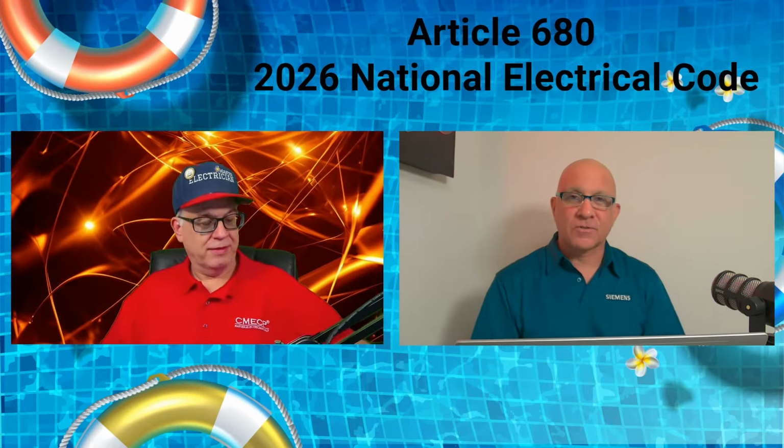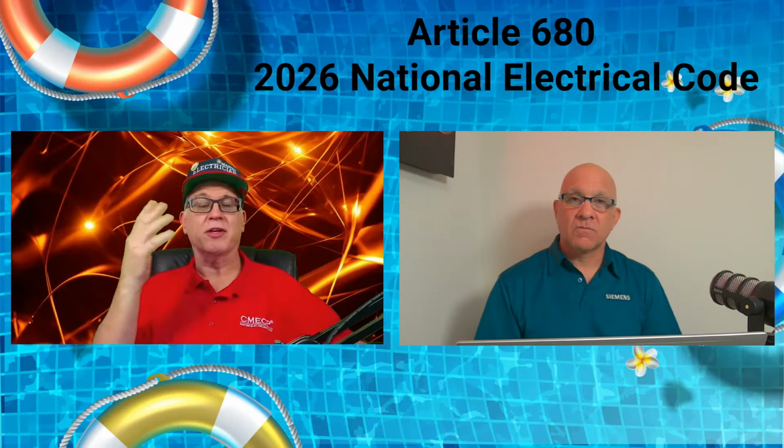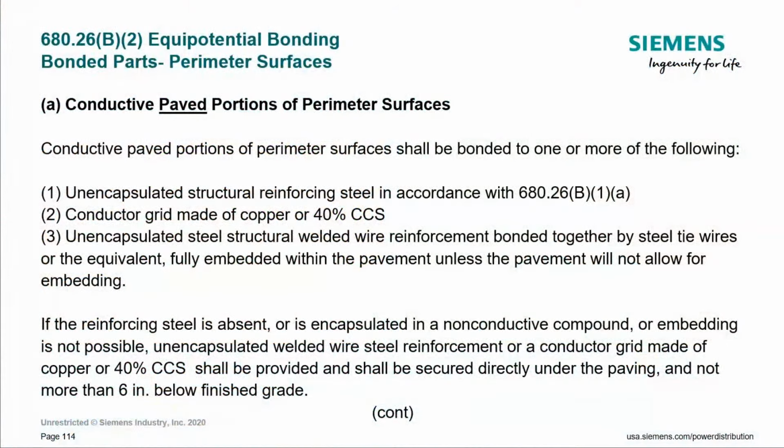All right, what are our options? What can we jam in this paving material to essentially bond all of this conductive paving material to get everything at the same voltage? Well, the code tells us, and based on Vincent's link, we can jam in an unencapsulated structural steel or reinforcing steel rebar.